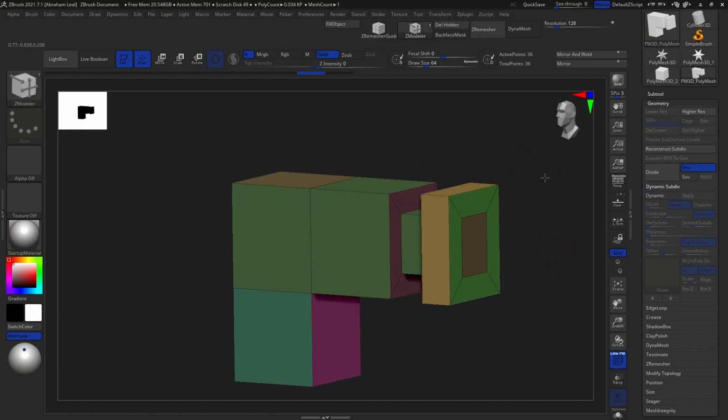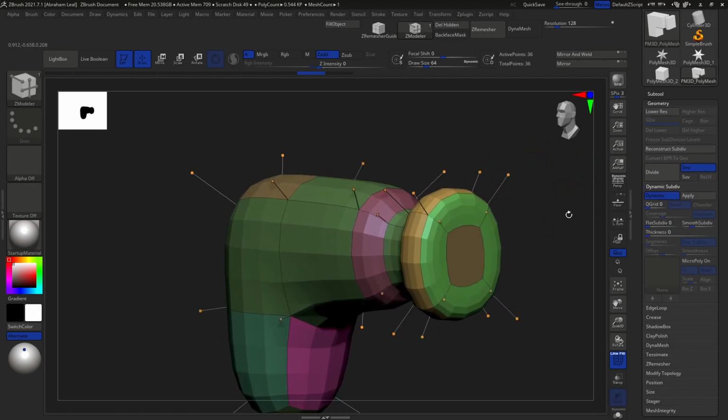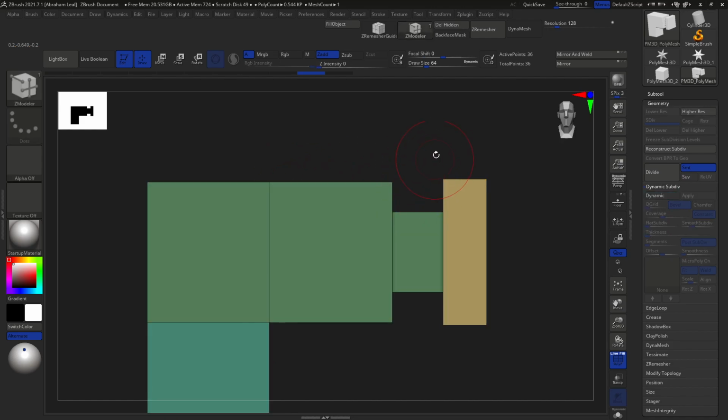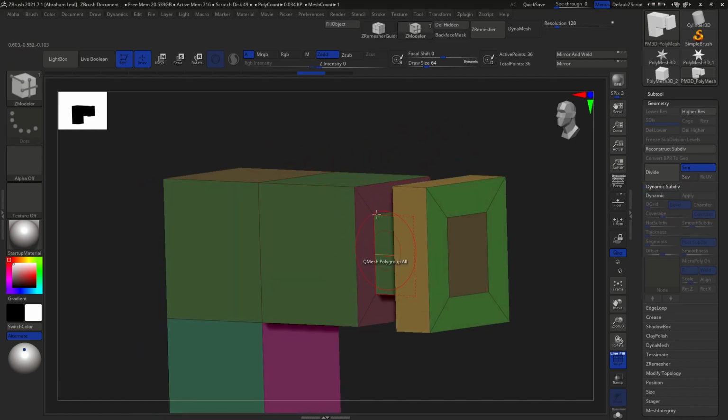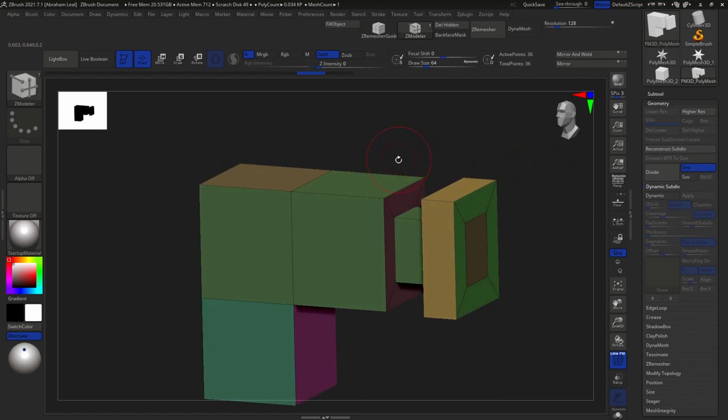And here's where one of the most important principles of hard surface comes into place. That is support edges. Anytime you do a subdivision modifier, what's going to happen is the 3D software is going to try to average out the distance in between the points. So if we want a hard edge, if we want this side of the little gun here to be a lot tighter, a lot sharper, we definitely need to have another edge loop right here. And there's a lot of ways to do it.